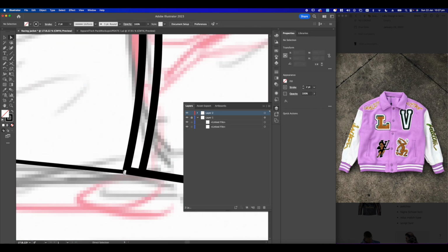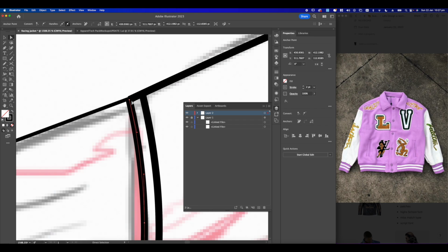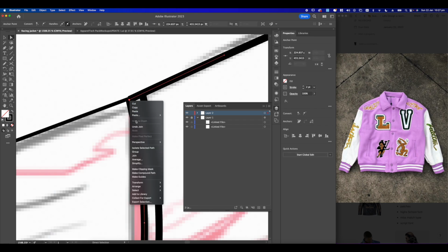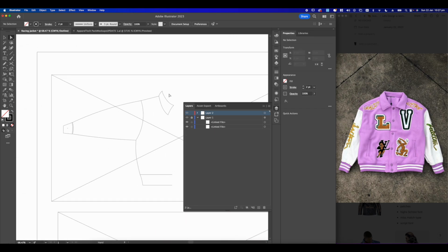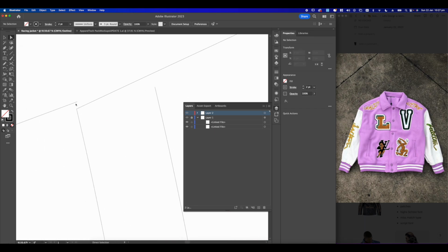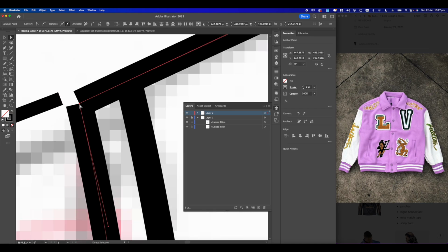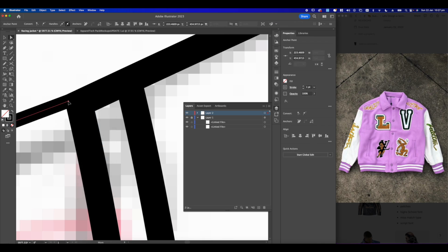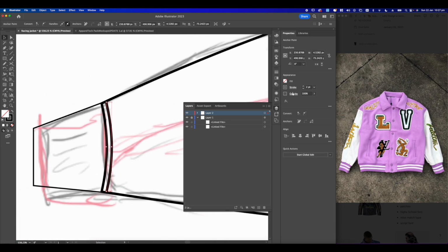And this way we can introduce a stitch line that's perfectly aligned with our original outline of the garment without having to draw this line in again, unless you're doing custom stitching in the areas to make some sort of pattern or something like that. This is probably the easiest way. Make sure to go back and close off all the points that you accidentally opened up, just to make sure everything is looking good. Down the line, you see there's points that I kind of mistook and forgot about, and it does come back to bite you if you don't go back and edit those points.